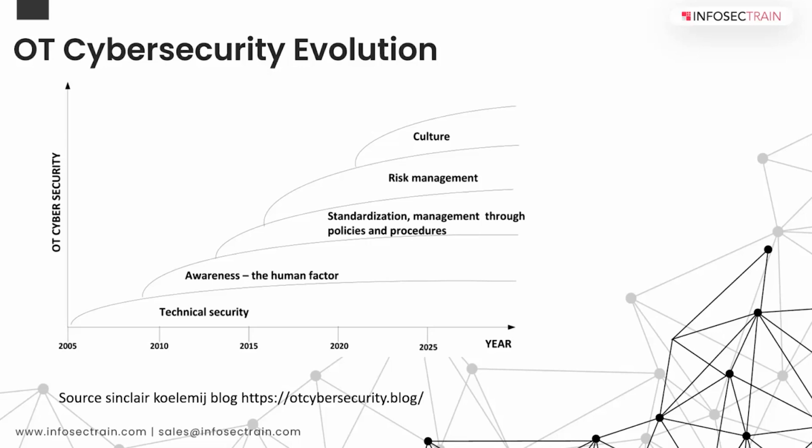When we take a look at OT, the priorities are totally different when we observe it. Especially in OT systems, industrial facilities, and critical infrastructure operations, the premise is safety, reliability, productivity. It doesn't mean that CIA doesn't apply. Of course, in OT cybersecurity, based on the standards and certain guidelines, we have something called AIC: availability, integrity, and confidentiality. Confidentiality requirement is very rare, but availability and integrity are the most important aspects.